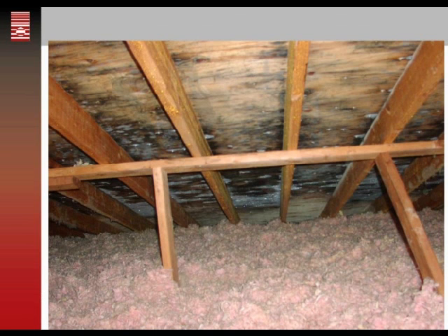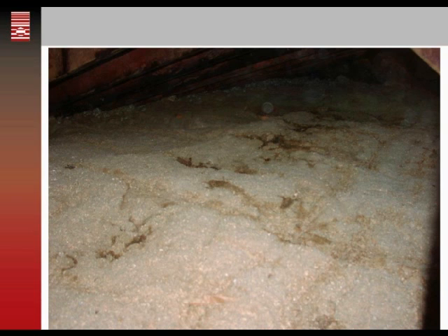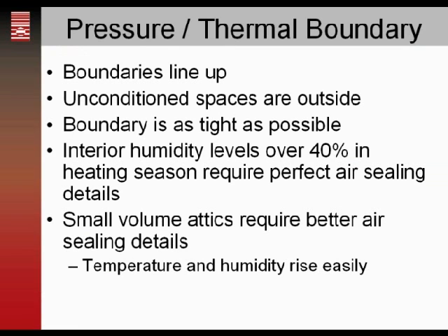Sometimes there'll be visible signs that there's been ongoing issues. So even if you don't have extreme temperature conditions, you can see by the discoloration of roof sheathing or active mold growth that there's been problems up there. Other times there'll be drips on top of the insulation if frost has been melting, and people can get pretty creative at trying to catch roof leaks and water drips.